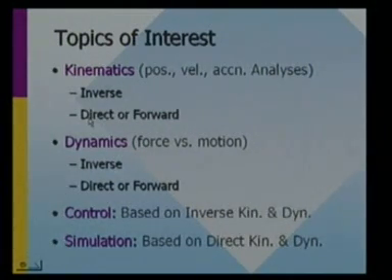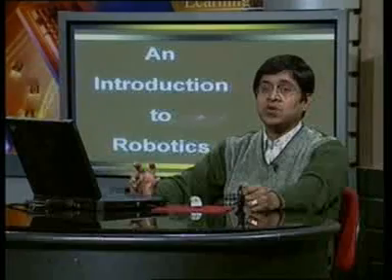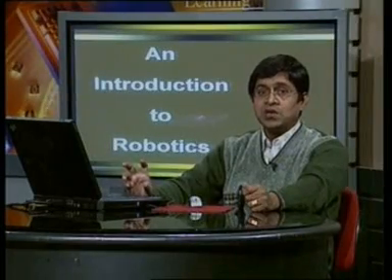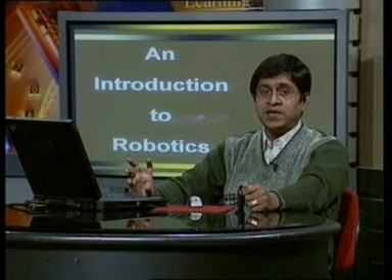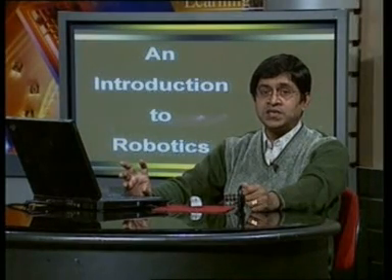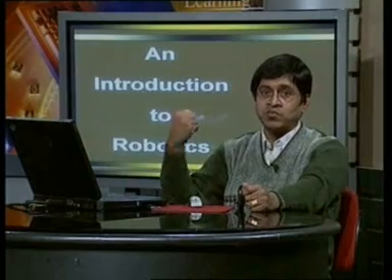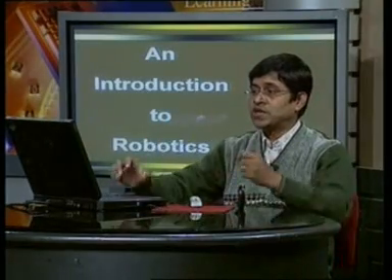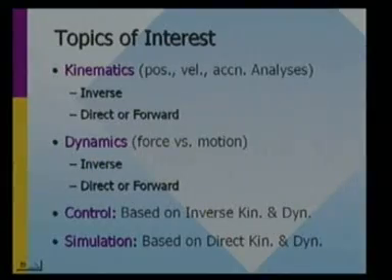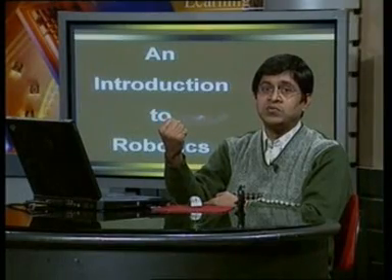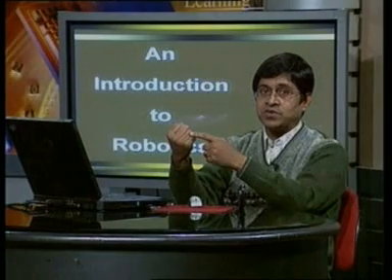Inverse kinematics means if the position of the end point of the robot is provided, but since control has to be done through the motion of the joints. So, to calculate those things, to give in the end effector positions and orientations to find out what will be the joint motions, like here the joint motions, right. In direct kinematics, we do the reverse. If you give me this one, then I want to know what will be the end effector positions.